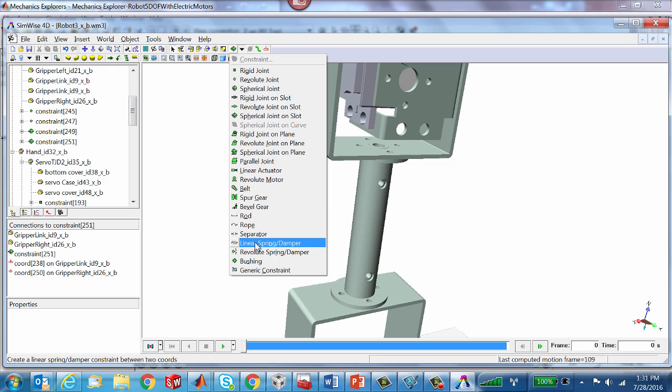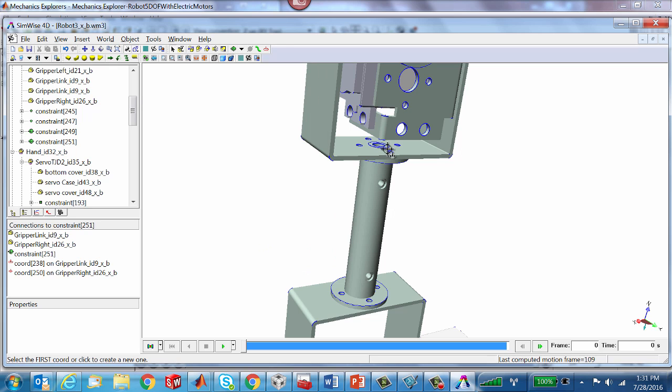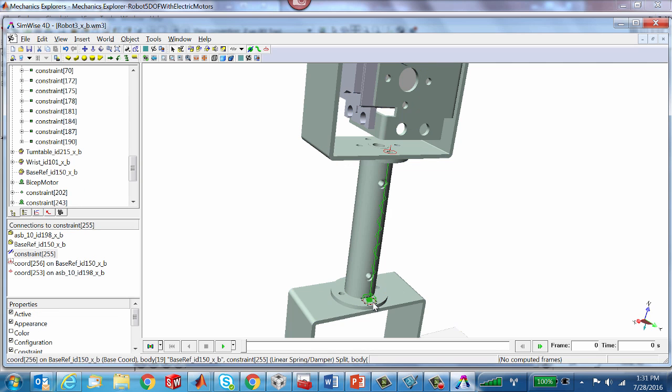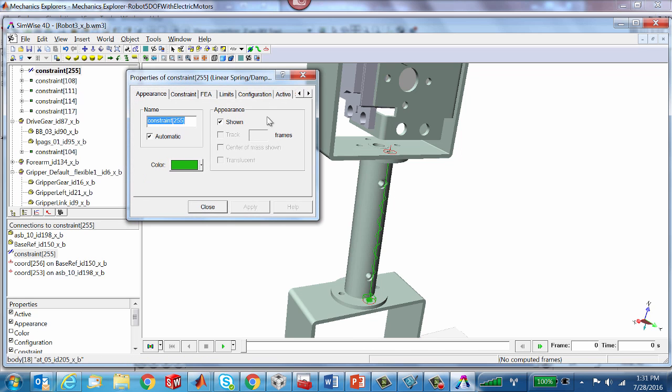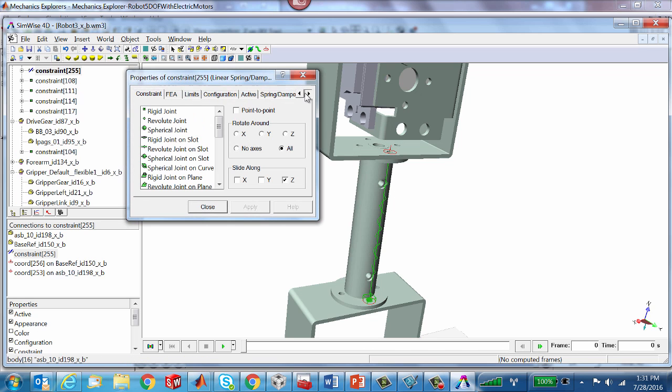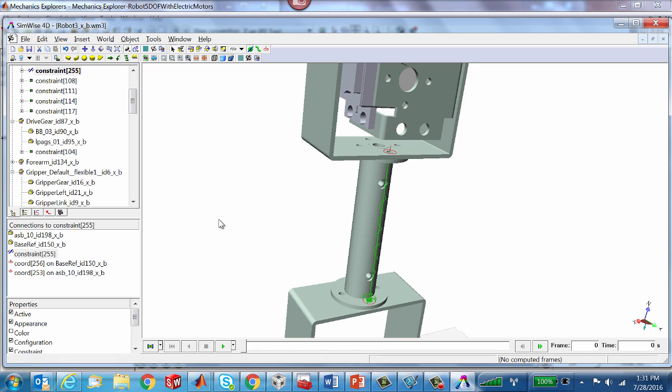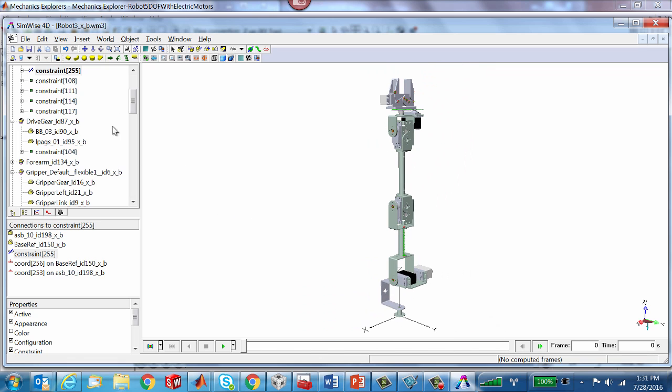And so again, I'm going to go get the tool to do this, and they essentially connect it from that point to that point right there. Okay, and you can see the icon right there, and we probably would want to go in and put the appropriate spring and damping and all that kind of stuff. It does automatically calculate for you from the current position what I'll call X0, the unstressed length of the spring. All right, but with that, we're about done.